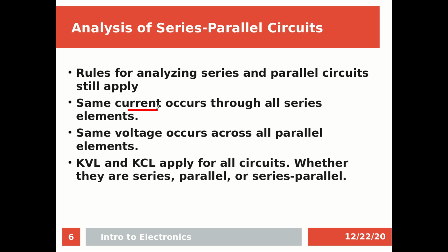So again the rules still apply. The same current occurs across all series elements, the same voltage occurs across all parallel elements, and for the rest you will use Kirchhoff's voltage law and Kirchhoff's current law, applying them to the other circuits or just to series branches or parallel branches.